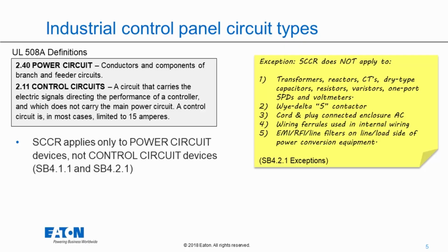You will note that voltage is not mentioned here, right? I know it's really easy for a lot of us to think, oh, the power circuit, that's our 480 volt part. Control circuit, that's my 120 volt or 24 volt DC. But that's not necessarily the case. You can have power circuits at those lower voltages, right, as it goes to an external load, that's a power circuit. I could have a 120 volt motor or a receptacle on the outside of my panel that anybody could walk up to and plug something in. That makes it an external load.